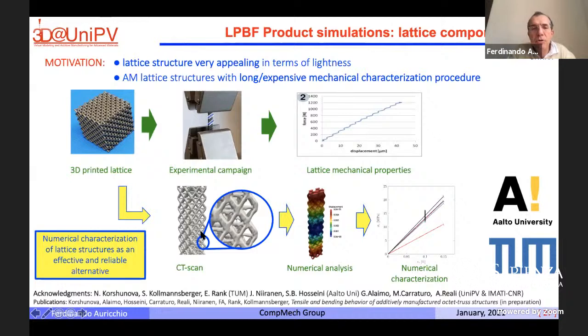So the powder dimensions are in the order of a few tens of microns. The laser spot is of the same order, and what people usually try to do is really to make these struts, this geometry, in the range of a few tens of microns. When you do these kinds of things, you start to have some problems. And what are the problems?